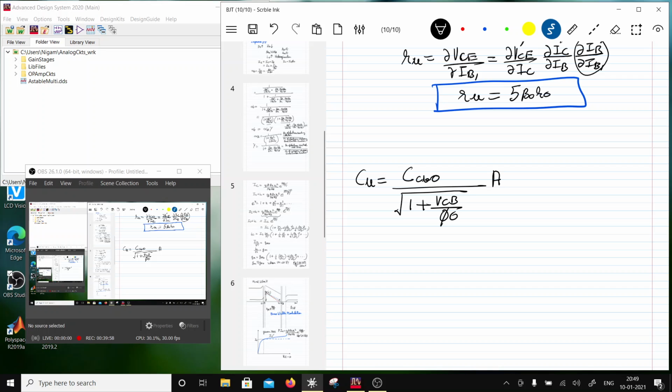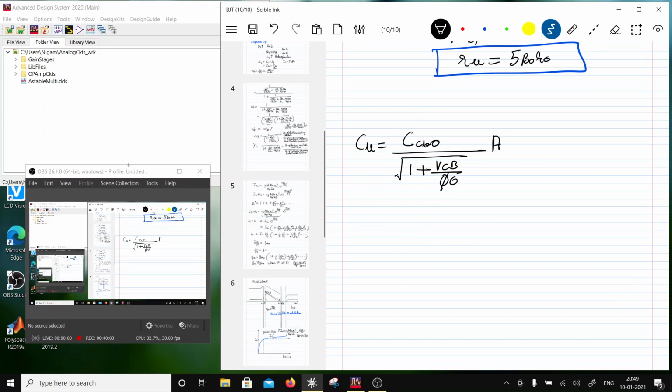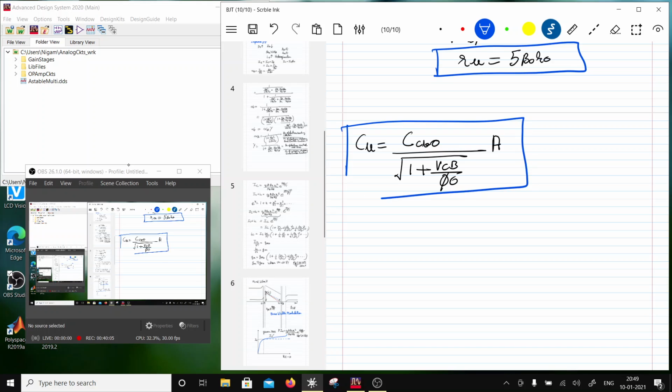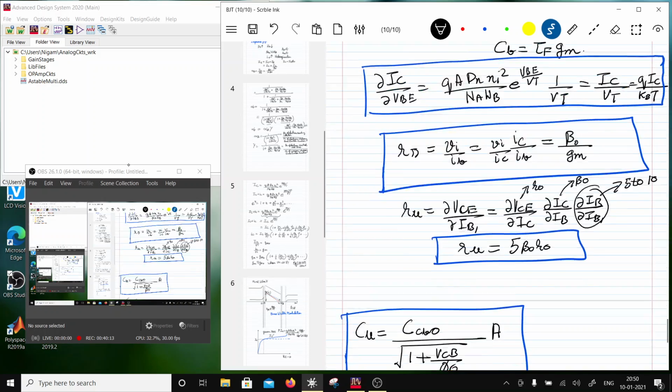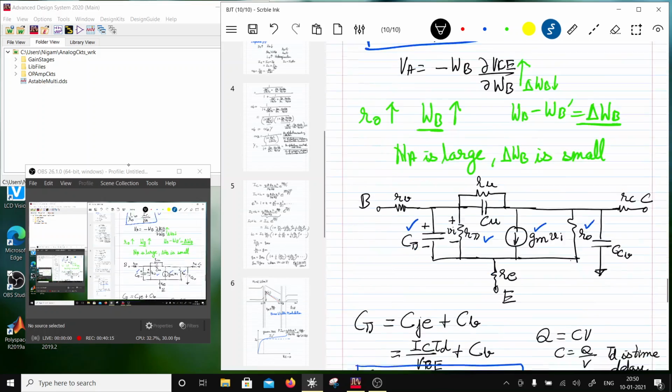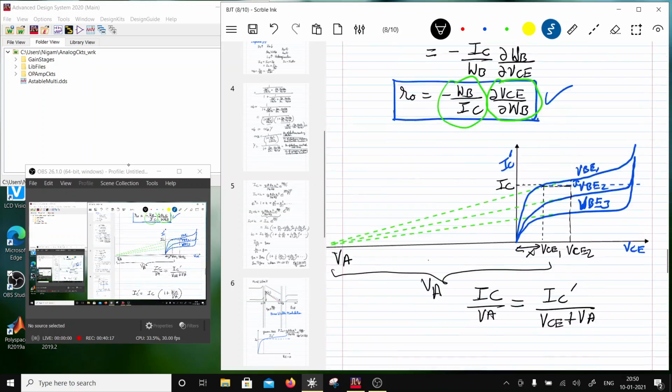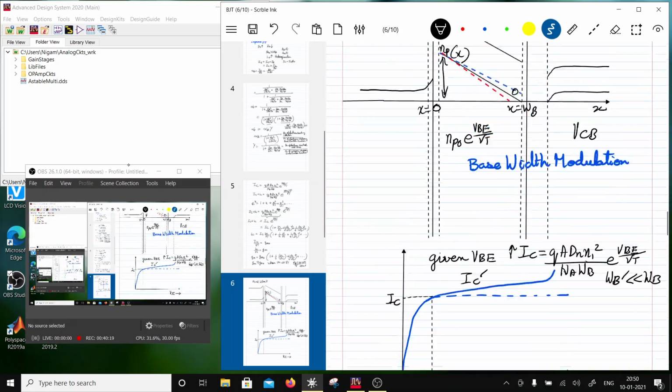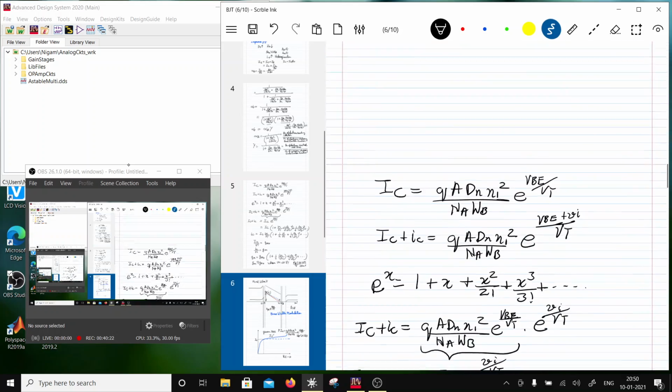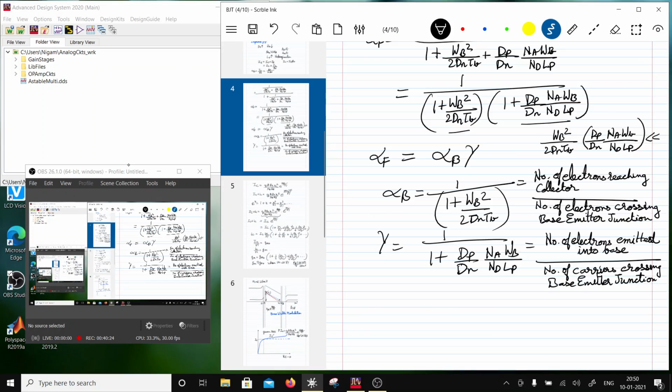So that will be the total capacitance C mu. And similarly you are going to have CB, which will be collector to body. If you see here, collector has a very large interface with the body terminal, because there is a sub collector involved, right?